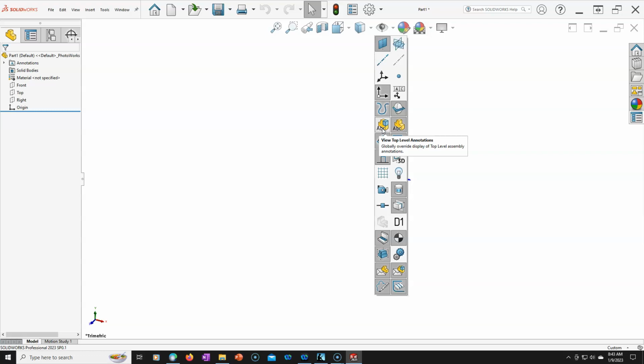And I would like to see origins, and I'm going to go ahead and turn off my sketch relations for this. So those are the little green and blue and orange boxes depending on the version. When you open up a sketch and the geometry all has the relations, they're good to begin with, but I can click on any one of those and they pop up. So I really don't need to see all of them all of the time.